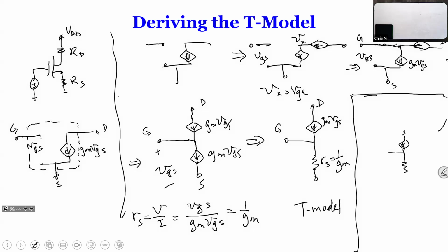Yeah, we're only doing the small signals, right? So, does the top become ground? Well, you tell me. So the top is your drain, this side is your gate, and the bottom is your source. So this is your lowercase rs, this is your gm times VGS. Now we have to find what VGS is in a little bit.